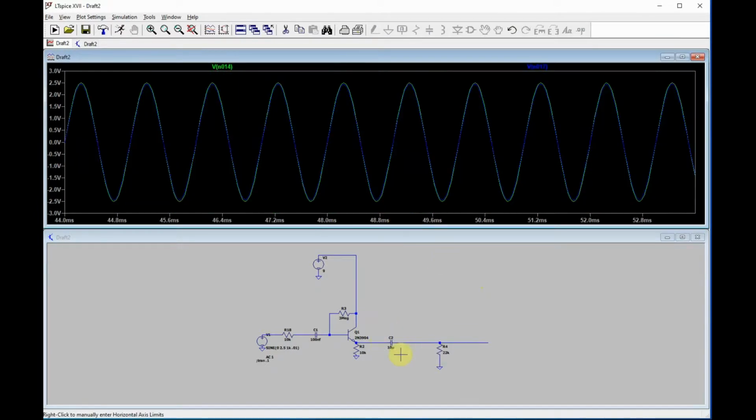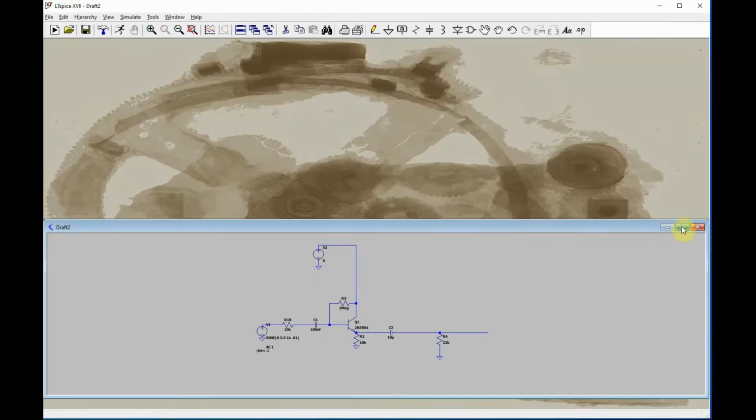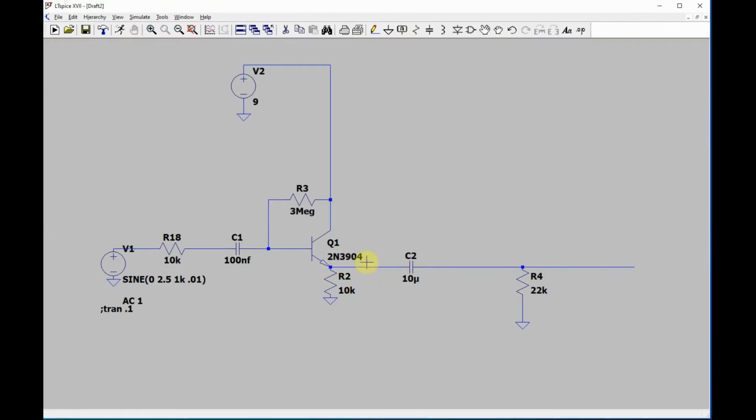So even though the output impedance is considered very low for small signals, when you get big signals there, the transistor has trouble supplying the load correctly, going back and forth with these really big swings. As another rule of thumb I use, if you have a 10K resistor here, I never put a less than 10K load on it unless the signals are really small.